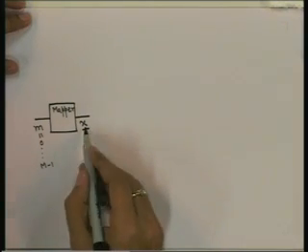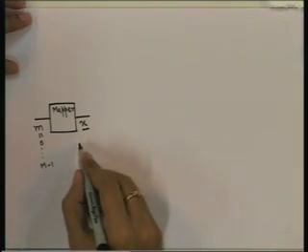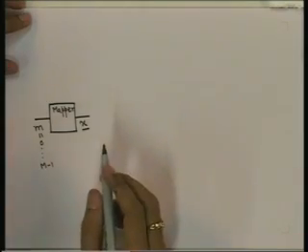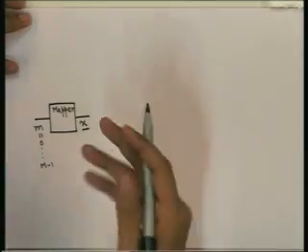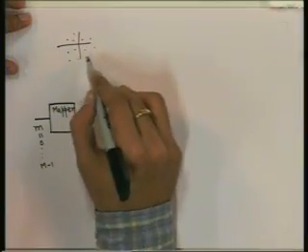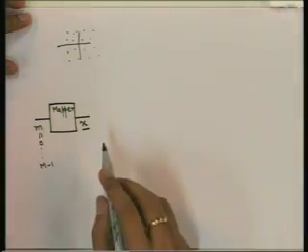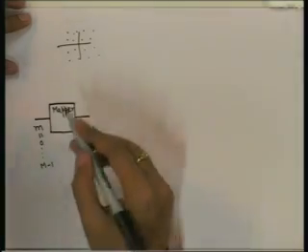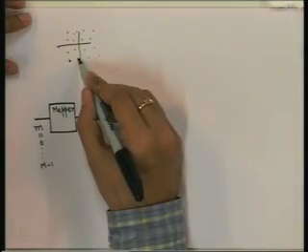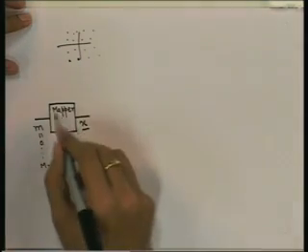This is the vector. So, this x may be x0, x1 and so on till x m minus 1. They are vectors. So, for 2 dimensional constellations like QAM, PSK, this will be a 2 dimensional vector. So, this may be one of the points from the 16 QAM constellation. For 0 we will suppose select this, for 1 we will select this and so on. So, that is the job of the mapper.